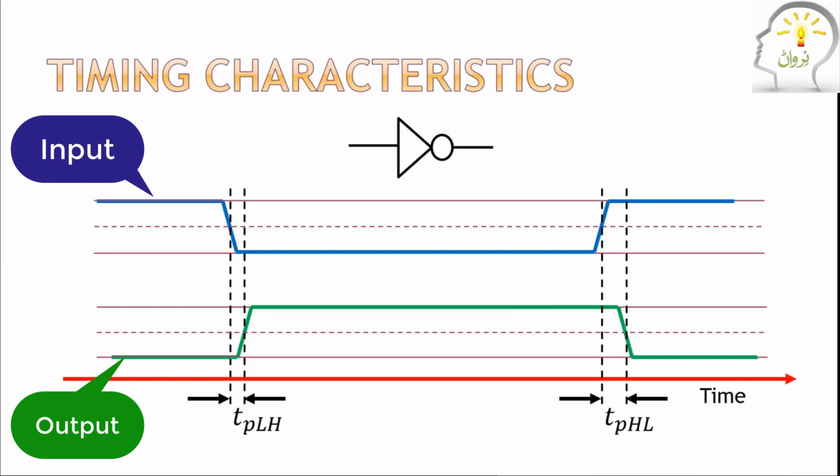Normally we do a lab to verify this in the laboratory. I will demonstrate this on the oscilloscope. I will show you this delay and this delay. Sir, will tpLH and tpHL in one wave be the same? No, they are never exactly the same, but they are similar values, very close to each other. Why not the same?